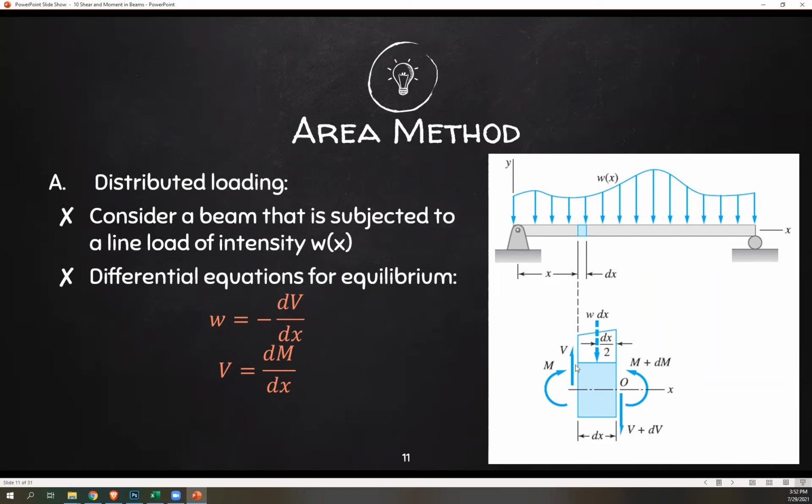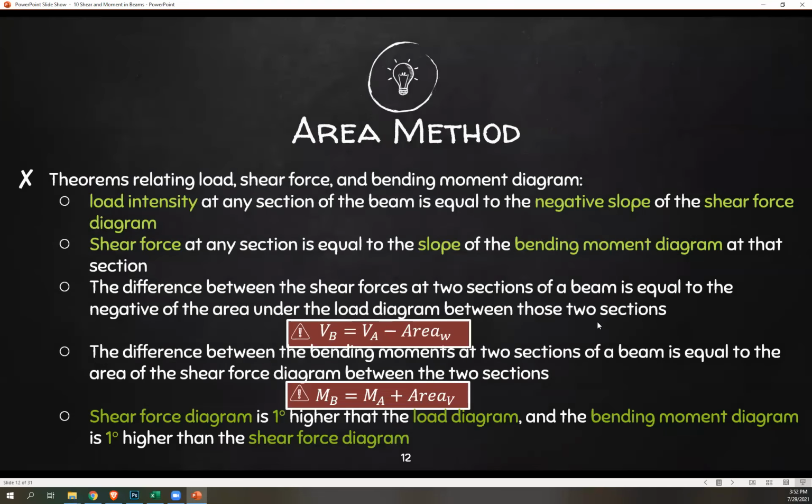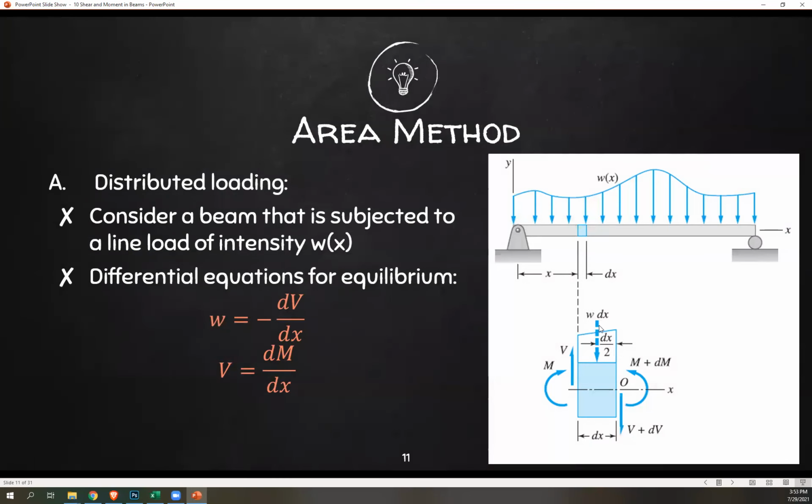Next, these are your resulting reactions, shear and moment reactions. So your shear here is upward, okay? And then you have this moment. And then afterwards, within this, there's going to be a moment due to this differential load along differential thickness dx.